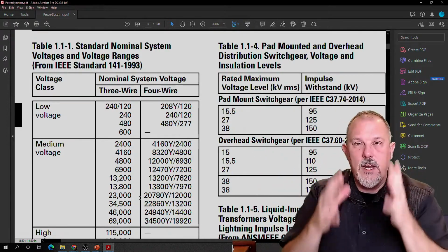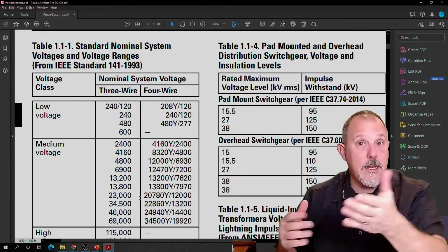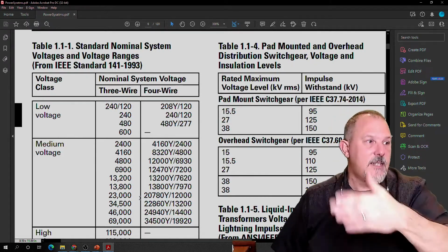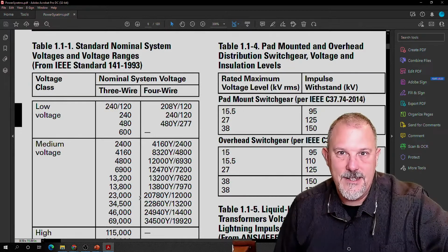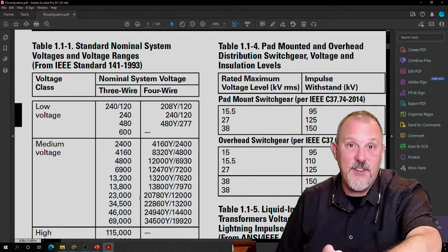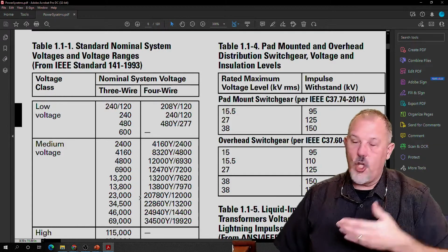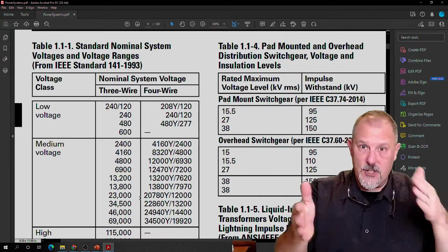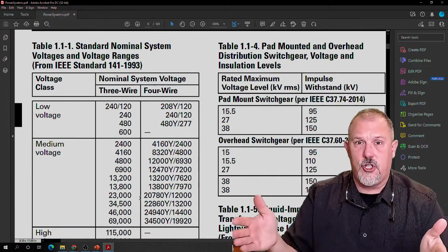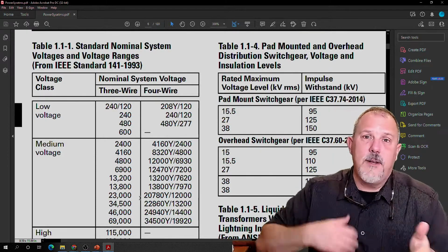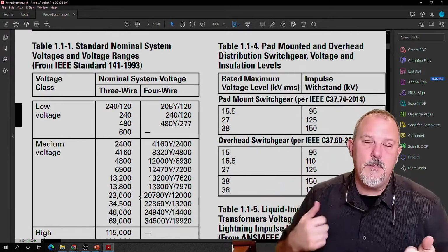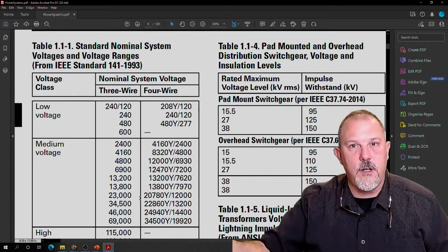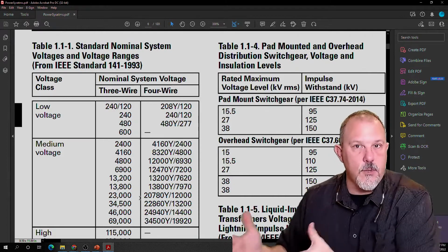So whenever you think about equipment like a motor, if I put 480 volts as the system voltage that you would apply it at, but your voltage is actually 470 volts, you would be below the rated voltage of the equipment. If I designed it for 480, plus or minus a percentage, because of voltage drop, you're not going to be at 480 volts unless you bump things up a little bit. You're going to be something less. So they anticipate that in the rating of the voltage of the rotating equipment, like motors.